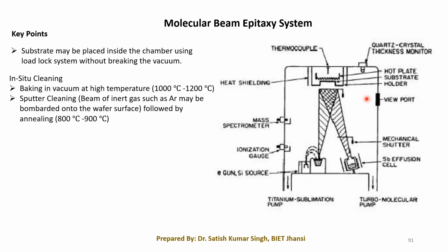Okay, so there is one particular mechanism attached, that is called the RHEED pattern. Okay, the RHEED screen. RHEED stands for reflection high energy electron diffraction. So we have to keep on monitoring the pattern of this RHEED. That will tell us about the quality of the grown layer, whatever we have, and we can keep on monitoring that quality.